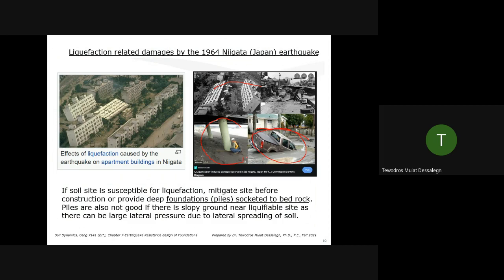So you see how the geotechnical engineer is making the big decisions. If you have a liquefiable soil, now you should be very careful what kind of structure you are recommending, what kind of foundation you're recommending. So either we should remediate the soil to avoid liquefaction, or use something like a deep foundation. We'll see in detail what kind of recommendation you'll provide.